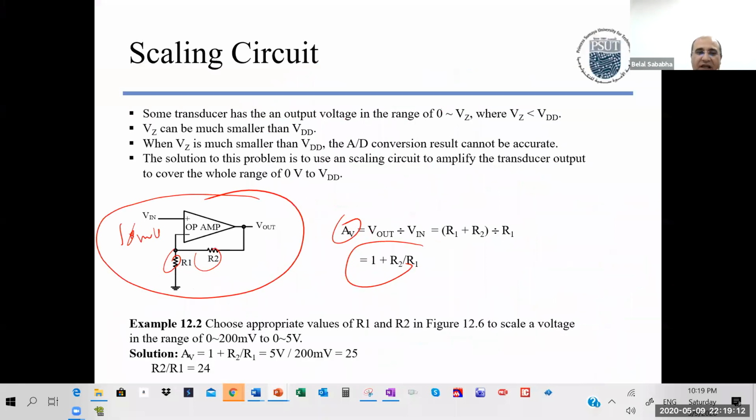Okay, so an amplifier is useful not only to make a small signal bigger. It's useful to amplify a signal to maximize the coverage of the voltage range that the A to D can understand, to get a better, more precise physical value you may want to sense.